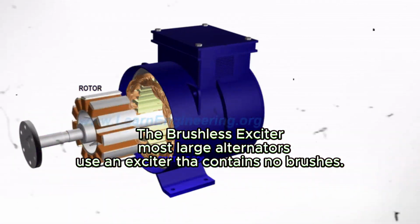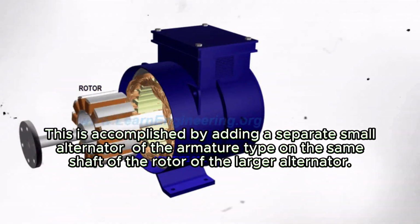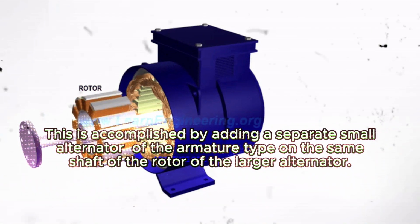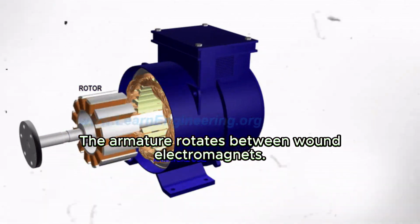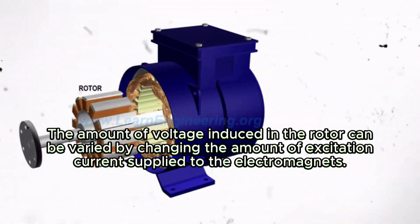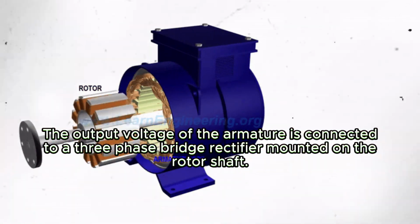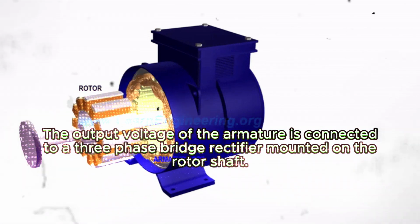The brushless exciter. Most large alternators use an exciter that contains no brushes. This is accomplished by adding a separate small alternator of the armature type on the same shaft as the rotor of the larger alternator. The armature rotates between wound electromagnets. The DC excitation current is connected to the wound stationary magnets. The amount of voltage induced in the rotor can be varied by changing the amount of excitation current supplied to the electromagnets. The output voltage of the armature is connected to a three-phase bridge rectifier mounted on the rotor shaft.